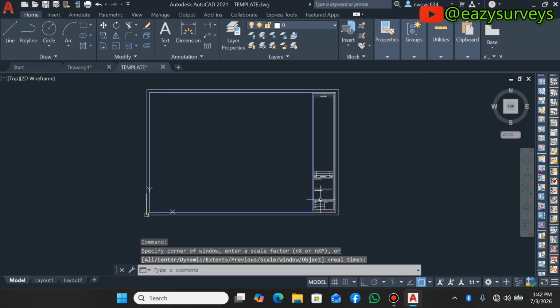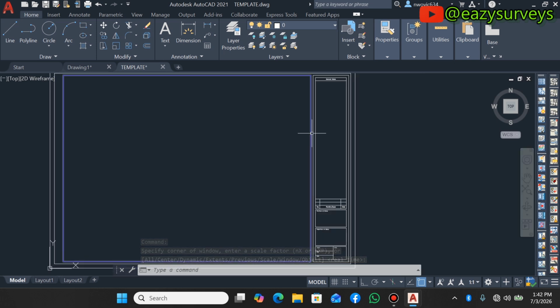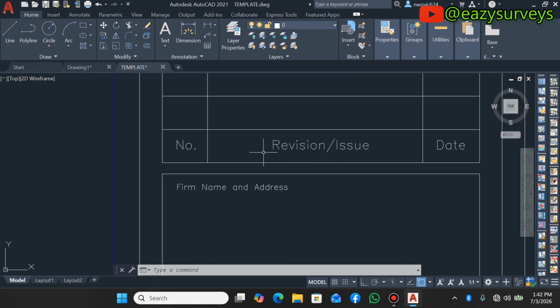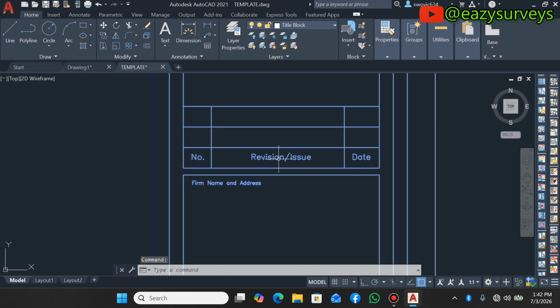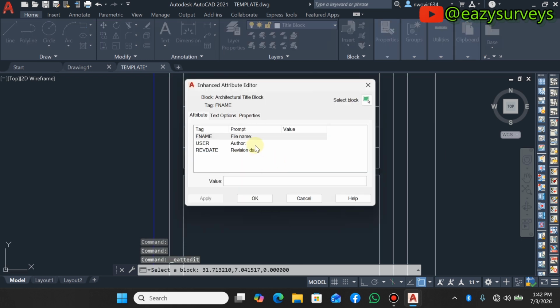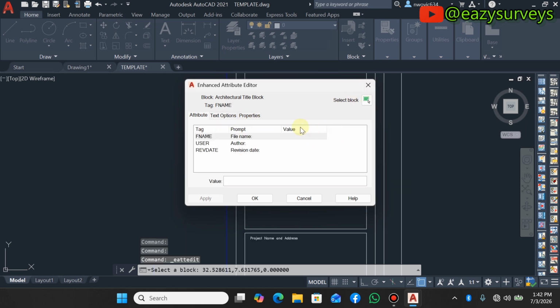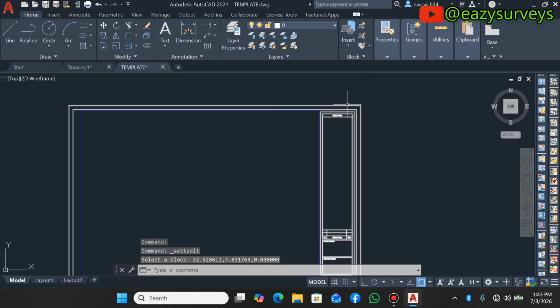So this is how to load in AutoCAD default drawing templates or title blocks, depending on what you want to make use of it for. You can see that all of these texts are yet to be editable. It says you double click and come to text options to start making all those general adjustments. But for convenience's sake, I advise you use the explode option to make the text editable.